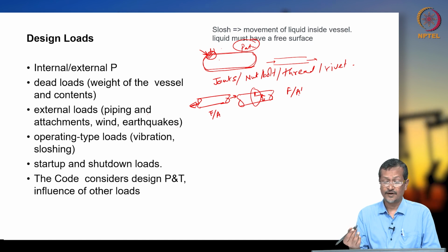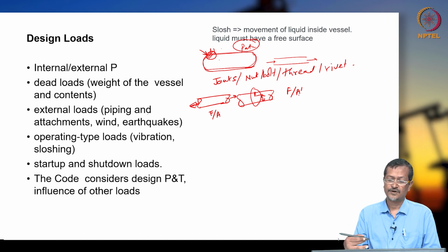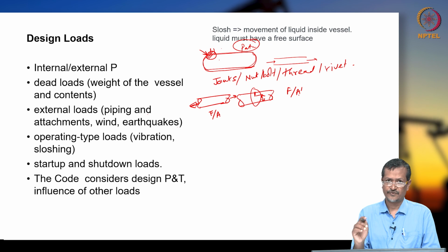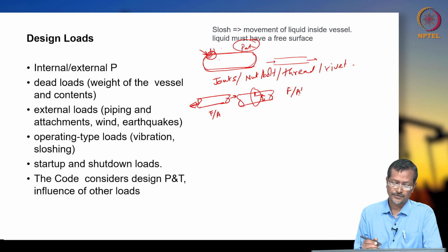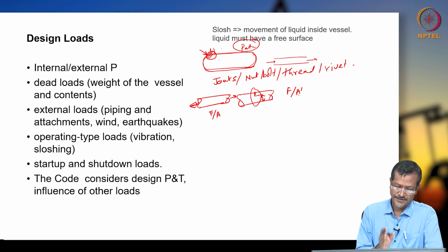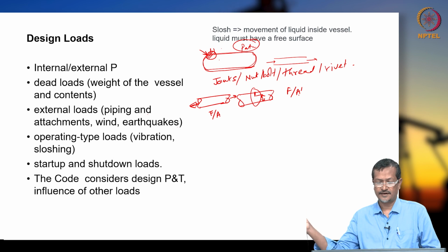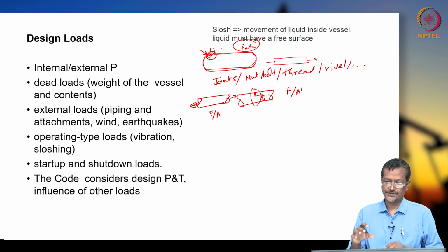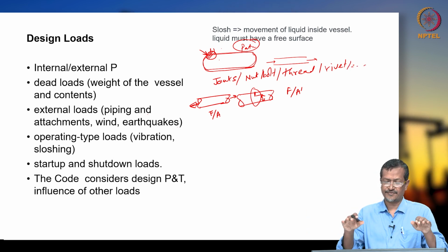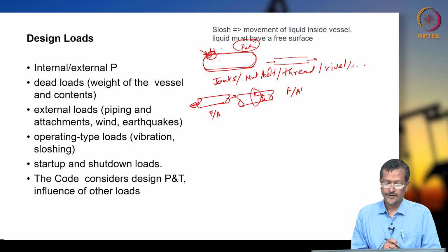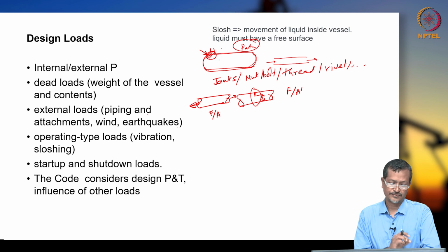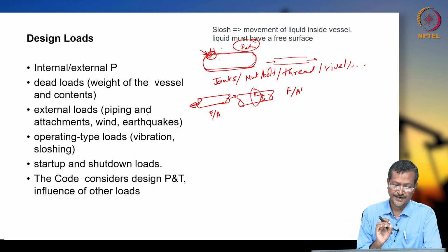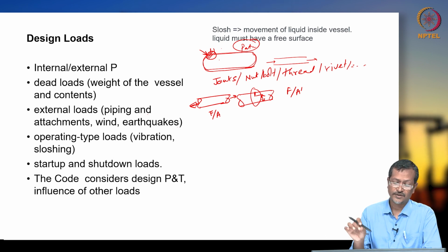Now you have a lower area. Lower area means you get more stress. More stress means failure probability is higher, and breaking will start there only. Okay. So whenever you have any mishandling, piping, attachment, like joints, nut, bolt, thread, rivet, or any other thing which is creating unevenness on the surface, that will give the breaking point or weakest point. So you have to look at those points also. Whenever you are designing, you have to consider all these factors.